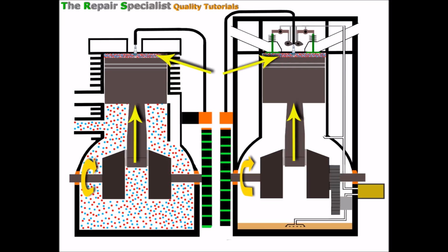Of course, it's top dead centre on compression stroke, so we've compressed all that air and fuel, and now we're ready for a spark. And that spark will now be generated because we've got the magnets there that are passing the coil packs just at that point at the top on the flywheel. So it's producing the current and it's going up the HT leads and down to the spark plugs. This of course happens more or less in an instant, but there it is, the spark. And the result is that instant explosion, that combustion there.